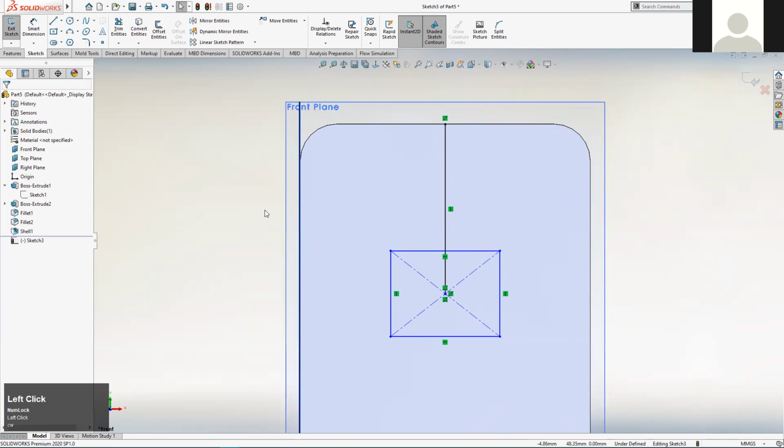So the last little step of setting this sketch up is to click on our line that we created there, because it's a solid line. It's not construction geometry at the moment. So it's ruining our solid boundary here. So we want a closed boundary, and we haven't got one. We've got this line cutting in to the center of it.